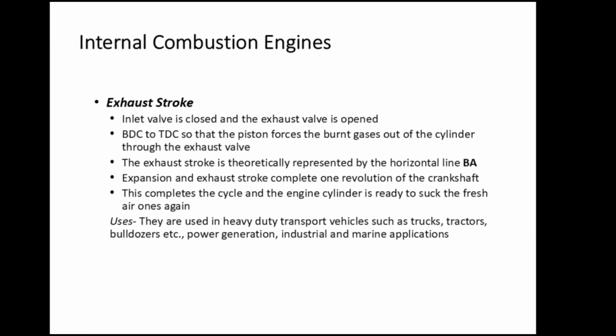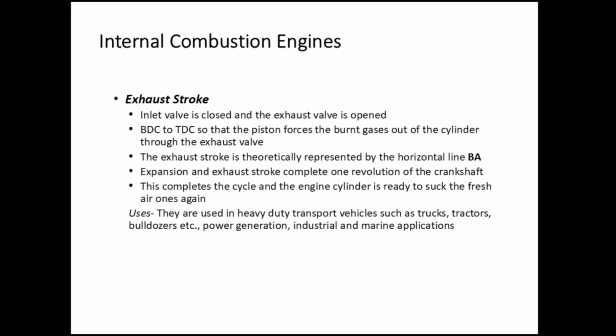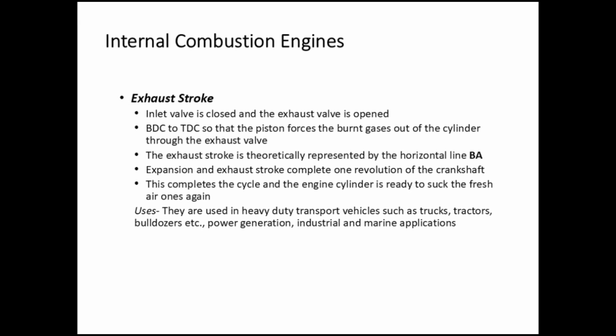Internal combustion engines. Exhaust stroke. The inlet valve is closed and the exhaust valve is opened, BDC to TDC, so that the piston forces the burnt gases out of the cylinder through the exhaust valve. The exhaust stroke is theoretically represented by the horizontal line BA. Expansion and exhaust strokes complete one revolution of the crankshaft. This completes the cycle and the engine cylinder is ready to suck in fresh air once again.